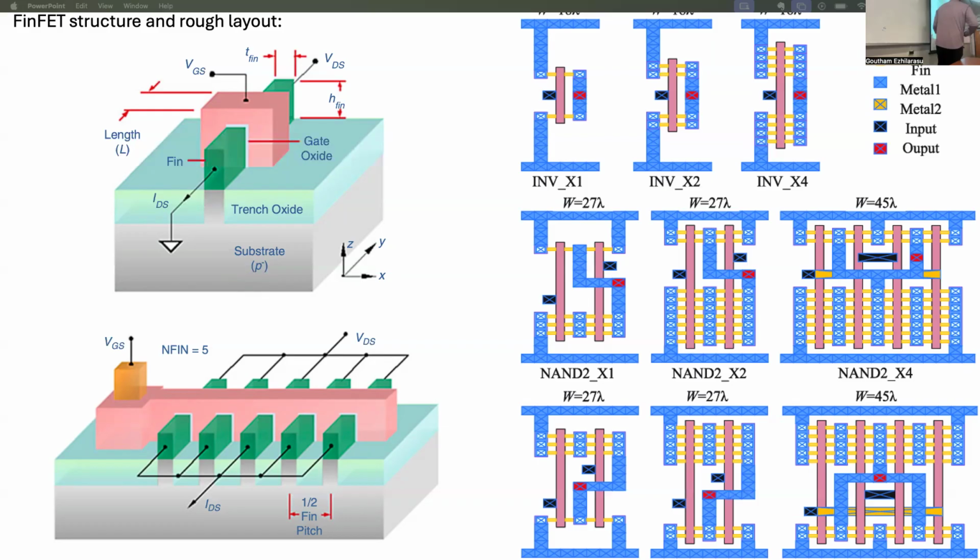Now, if you want to know the width of this transistor, you have to add, you have to go this way, up, and so on, right? So that whole thing is the width of the transistor, correct? And the length of the gate itself is just going to be this, because this is the place where you actually have the channel formed, the inversion layer, and then the transistor begins conducting, right?